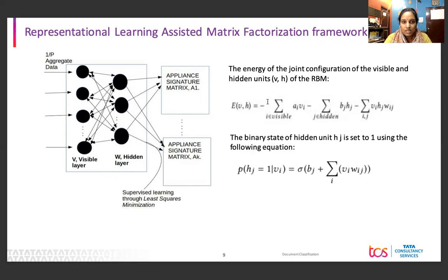The mapping consists of information about which appliance consumption behavior corresponds to the input smart meter data. In this work, we have used Restricted Boltzmann Machine because we know they are good approximators to the input data, and they are very efficient in learning latent representations. In electricity load disaggregation, latent representations refer to the learning of the typical magnitudes of energy consumption, the typical durations of each instant.